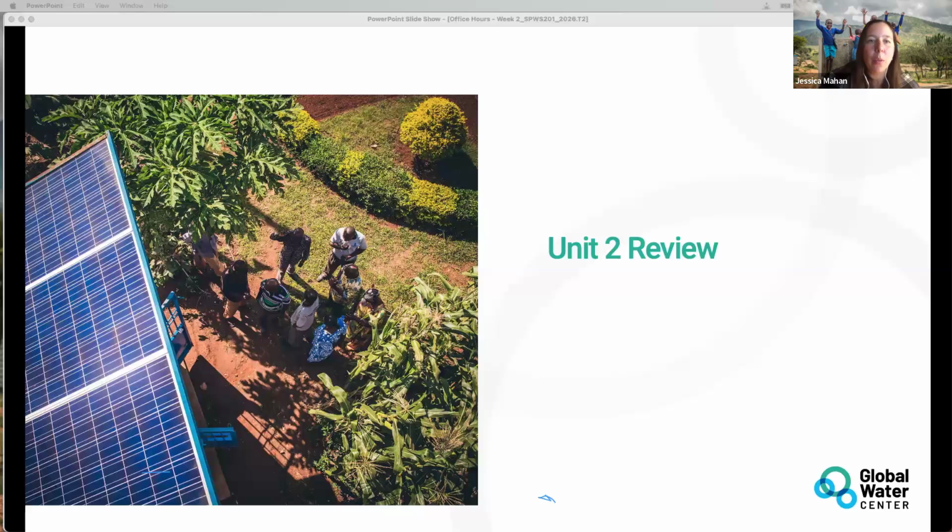Like Zirahun was saying, we get a more realistic picture of what the well is going to be able to do long term if we pump for 24, 48, or even 72 hours. So we might say that's best practice. You might be able to pump a well for 6 hours and get an abstraction rate, but that doesn't mean the well can withstand that for 24 or 48. So that's what we hopefully need to look at when we're doing the longer pumping tests.